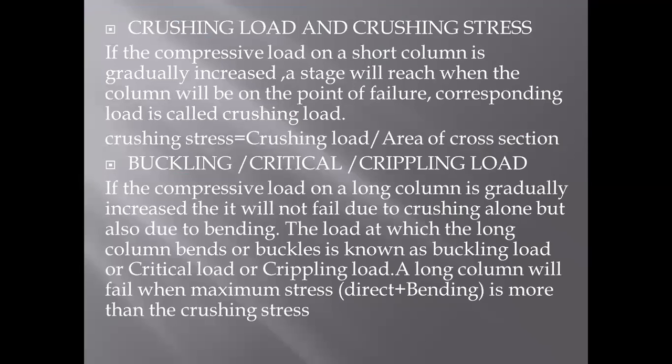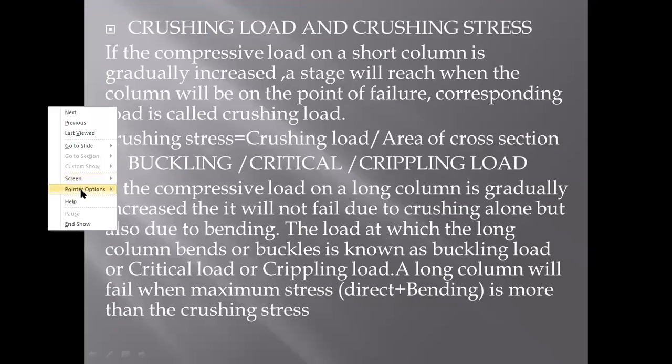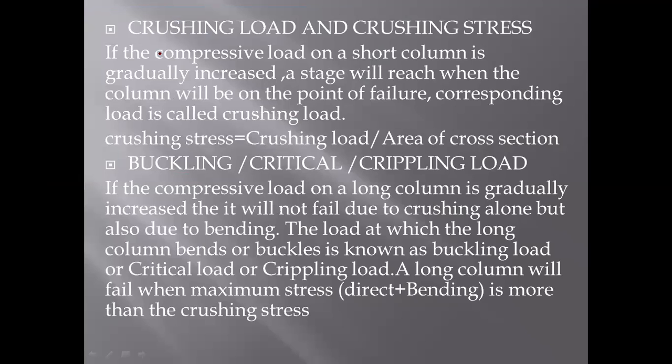Okay, now what is a crushing load or crushing stress? If the compressive load on a short column is gradually increased, means you are applying load to a short column and that load is compressive in nature, then a stage will be reached when the column will be on the point of failure. The corresponding load is called the crushing load.